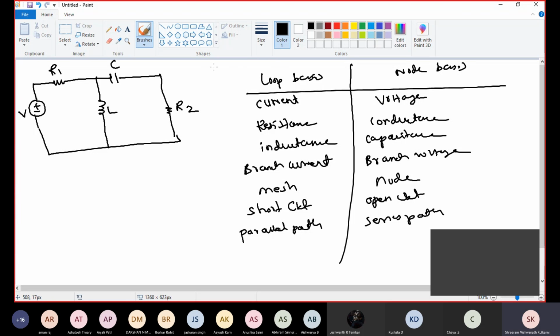Now, see this table. Tell me, voltage source will be replaced with current source. Resistance is replaced with conductance. L will be replaced with C. C will be replaced with L. Okay. Now, on this basis, we are going to write the dual of this. See here.